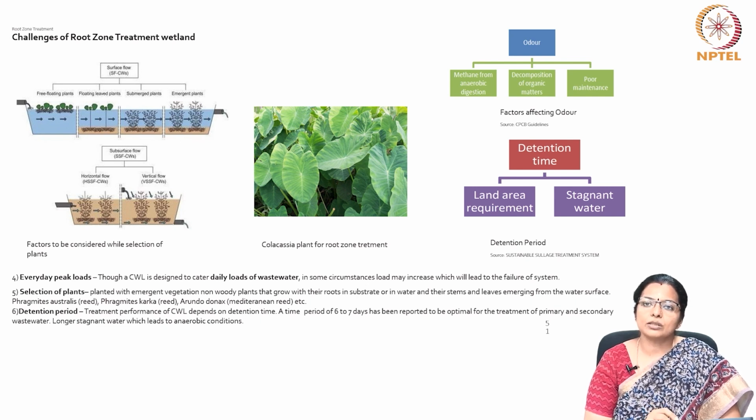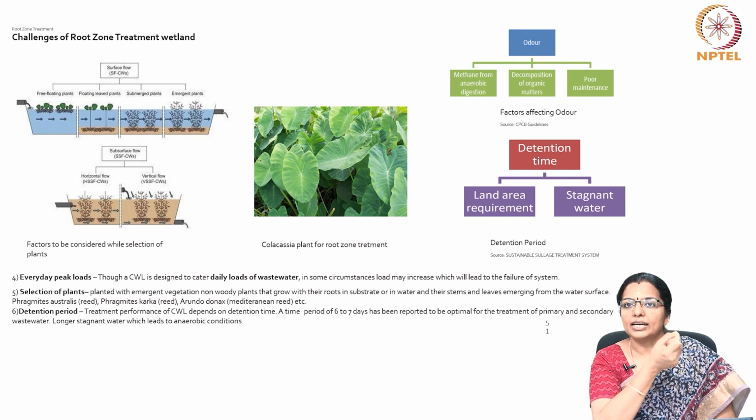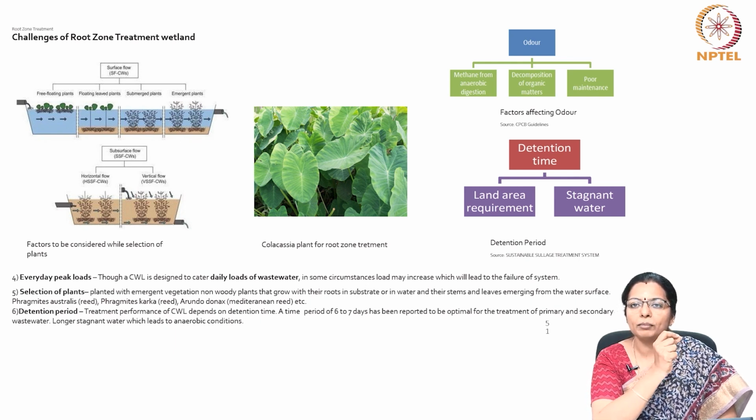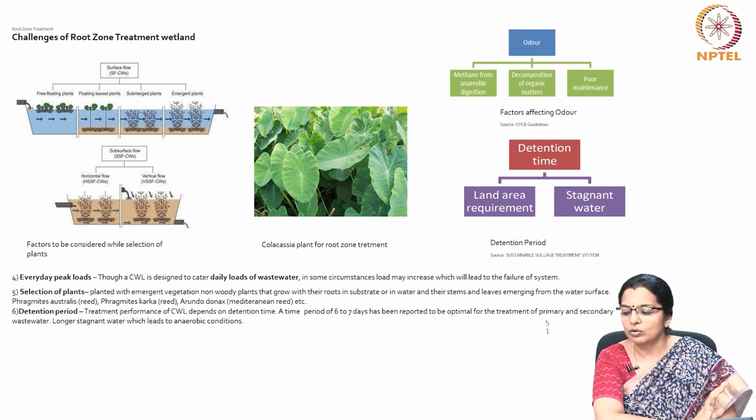Then next is the detention period. Treatment performance depends on the detention time. A time period of 6 to 7 days has been reported to be optimal for the treatment of primary and secondary wastewater. Longer stagnant water can lead to anaerobic conditions and can give out smell.